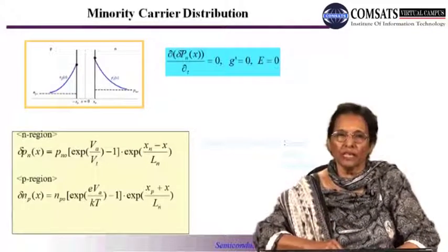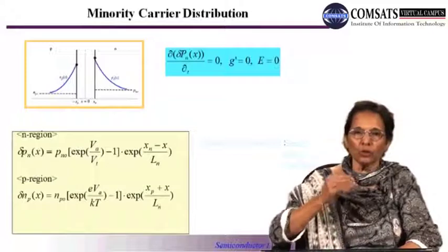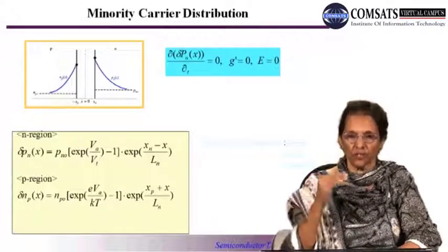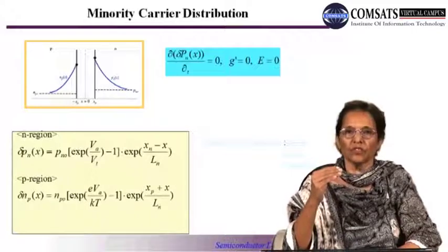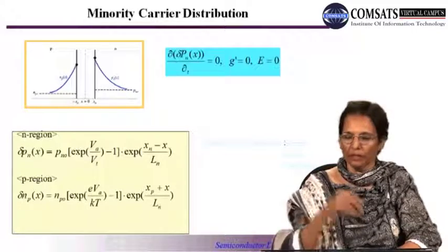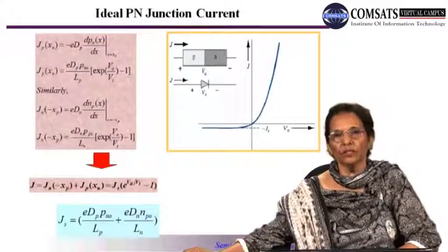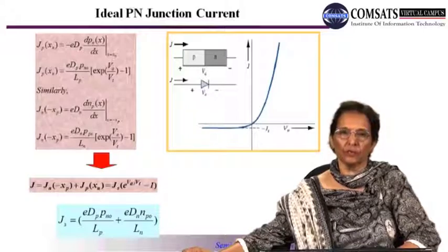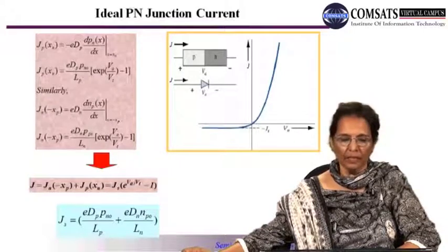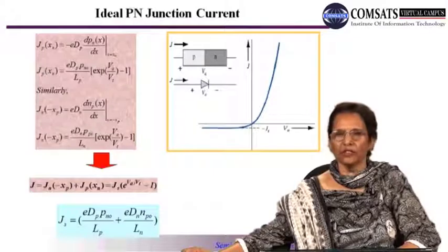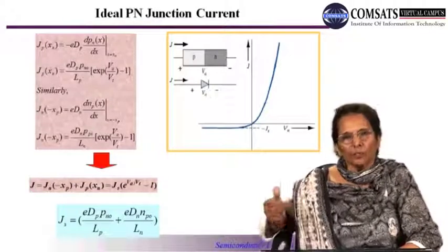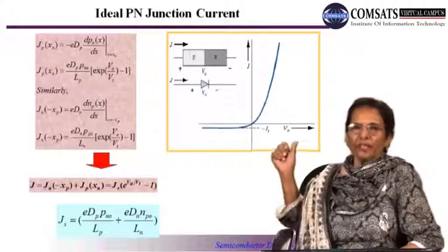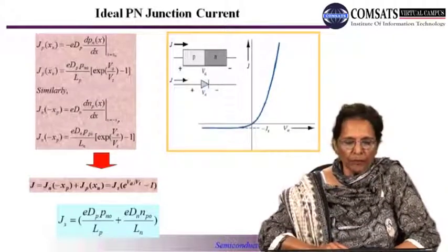Again, the bottom slide I have retained so that now you can correlate the schematic illustration of the carrier concentration schematically as well as mathematically. This transparency shows the quantitative expression for the current densities J in an idealized PN junction. Repetition of the same ideal IV characteristic is on the right hand side of the transparency.